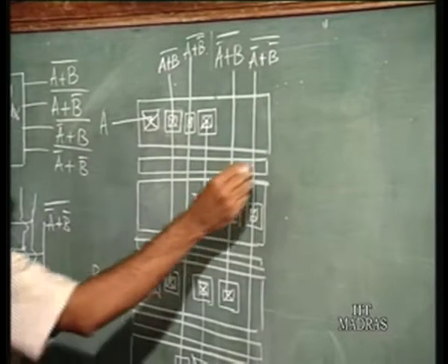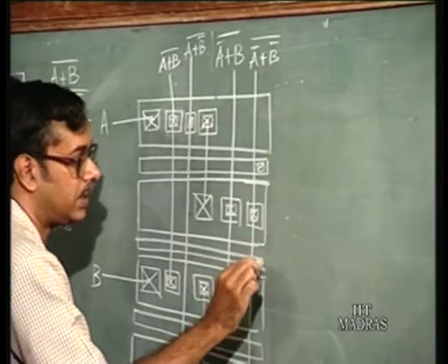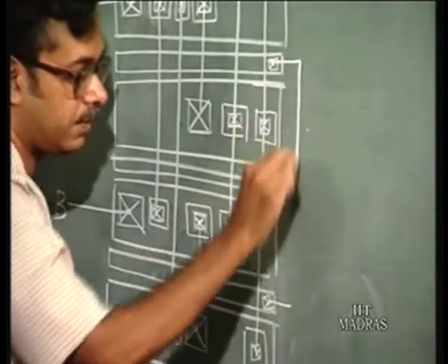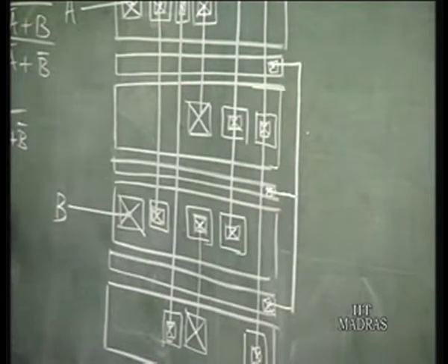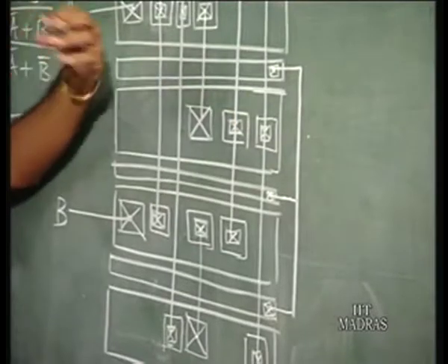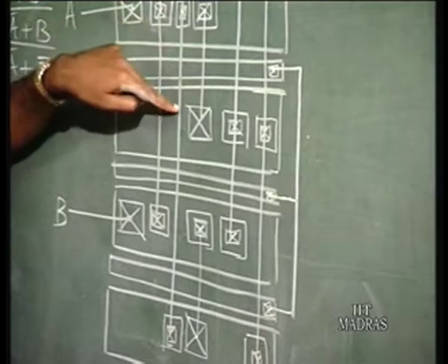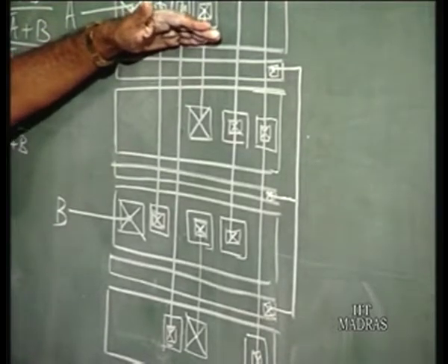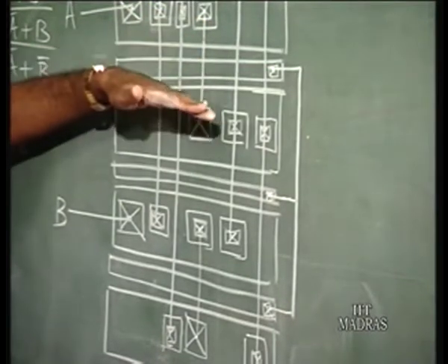The injectors, these are the injectors. This is one injector contact here, one injector contact here, you can short all of them together, and this is the injector. So basically what we have done is, these are the injectors, the injector that is of the PNP transistor. So this is the PNP. So the injectors are injecting holes into the base of the NPN transistors. So they are positioned in between the 2 transistors.